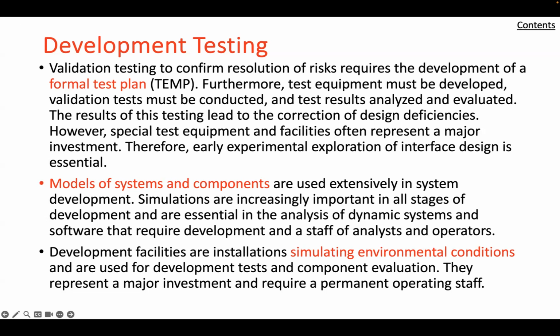8, identify the test inputs necessary to simulate the components and the output that measures the system's response. 9, define requirements for test equipment and facilities. 10, determine the cost and manpower. 11, develop test schedules for preparation, conduct, and analysis of the test. 12, prepare detailed test plans. And so there's a lot of things that need to be in consideration when we're looking at the development tests.